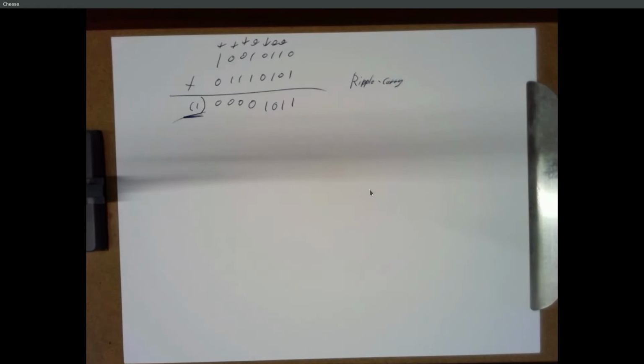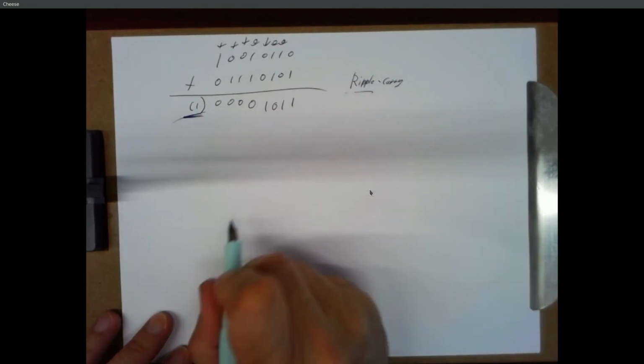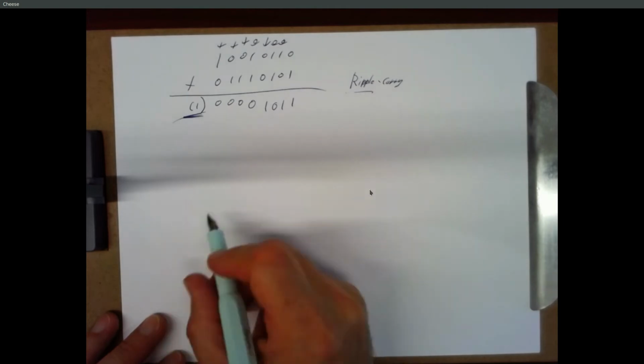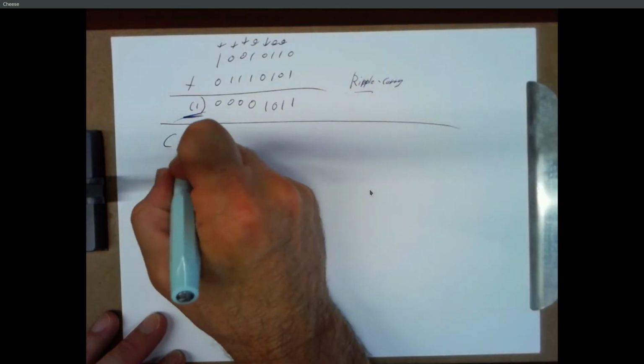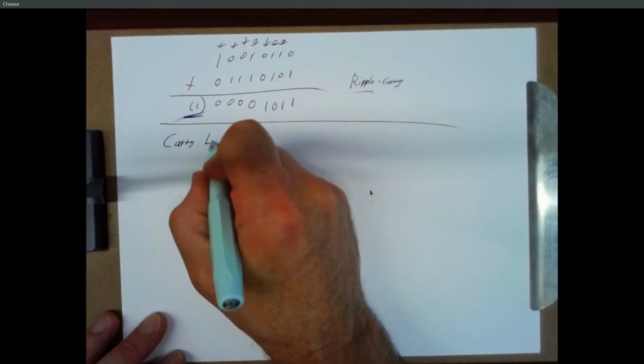And that can be a problem. So people have spent a lot of time trying to speed up arithmetic. And the most basic part of arithmetic is addition. So if you can speed up addition, you can speed up multiplication, because multiplication is just a bunch of additions. You multiply bit by bit, and then you have to add up all these numbers. So getting rid of this ripple carry effect is key to speed up. So one way to do this is to do what's called a carry look ahead.